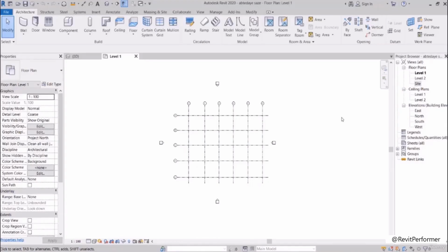So this is everything about designing, but a very important point here: I would always say that the 0 of the project should be in a specific and constant spot. In big projects, it's already told to you officially that this is the 0 spot and all the groups will work based on that. If you remember one of the projects where the center lines had crossed, we considered that to be 0.